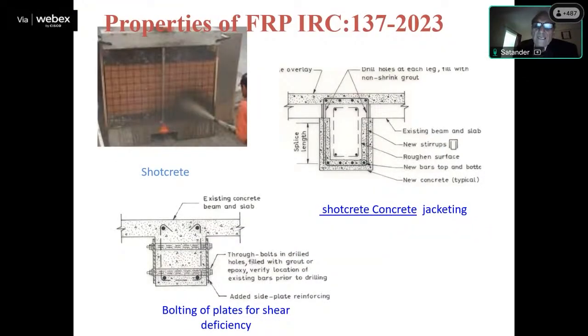Now regarding, suppose there is some fault here, this is a damaged girder. How to repair it? So make two holes here also, put some extra reinforcement. Then this is the extra one. This is called concrete jacketing, column or a beam. Or you can go for steel jacketing also. One steel plate here, one steel plate here. Or nowadays you can put FRP plate also. One FRP plate here, one other. Or single FRP. You can cover all the three sides with FRP plate also nowadays, because it is available.